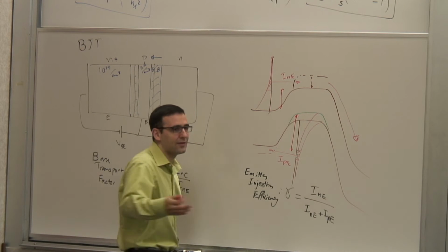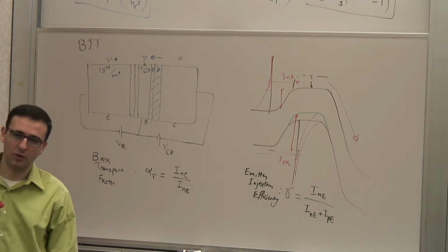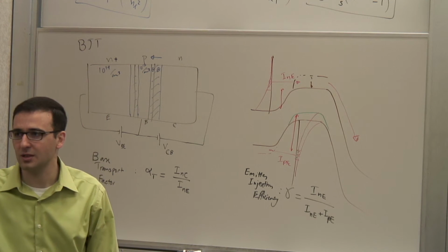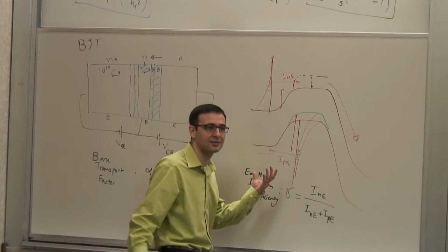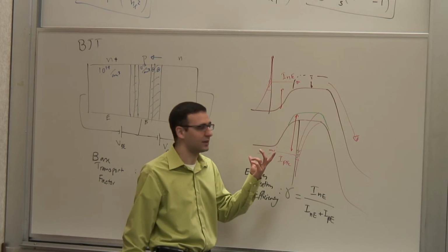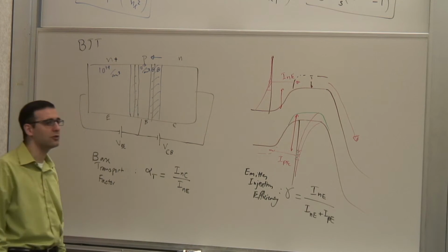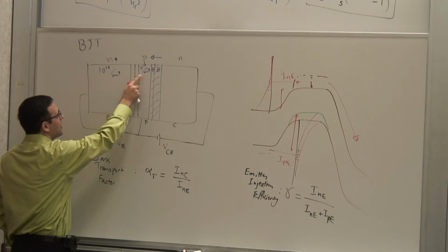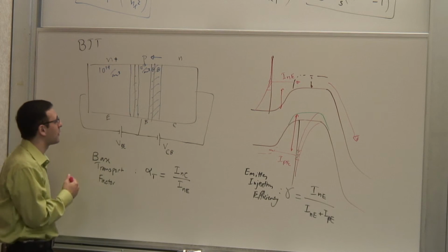Or, if you have a compound semiconductor, by controlling the ratio of the two components of the compound, or introducing a third element, you can actually create a different kind of semiconductor. This whole process is called band gap engineering, because you're modifying the band gap. Now, this is interesting, right? Because if you do this, what does it allow you to do? It allows you to relax this strong ratio, and we'll see why that's important. I'll tell you one reason why it's important.